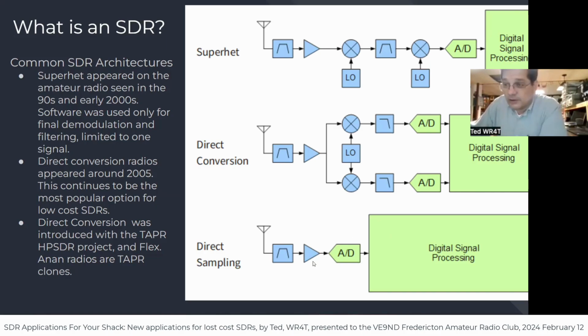And of course, there are different ways to measure dynamic range. Blocking dynamic range, 130 dB if you're just measuring blocking dynamic range. So you lose dynamic range with a DSP-based radio, but that really is only going to affect you when you're operating your radio very close to a high-power transmitter without filtering. If you have filtering, if it's another band, it doesn't bother you because you have good bandpass filters. So someone can be operating next to you on 20 meters. The good direct conversion radios have very good filters in them. It's not going to bother you. It's only when they're in the same band.